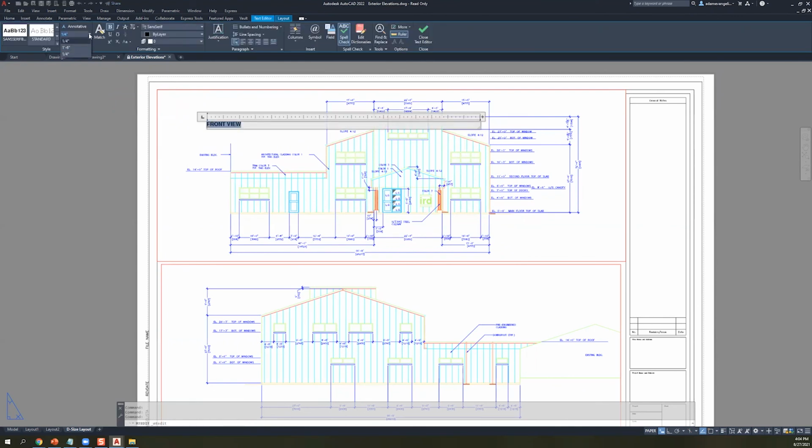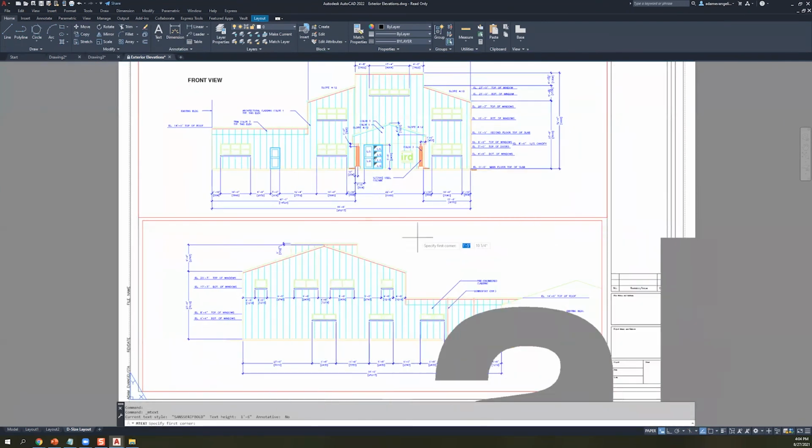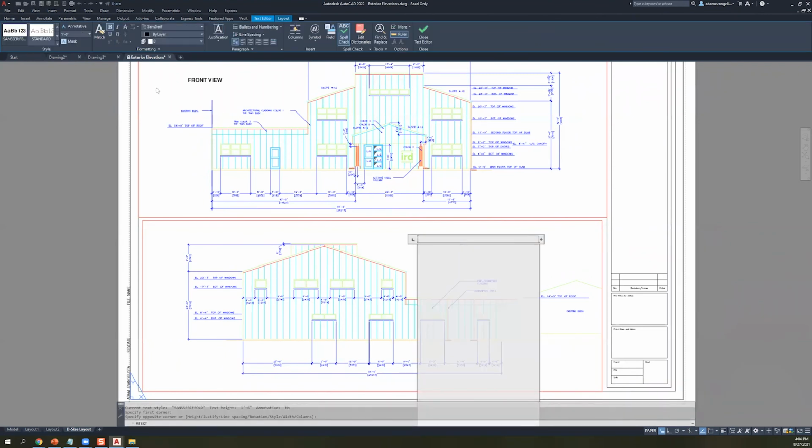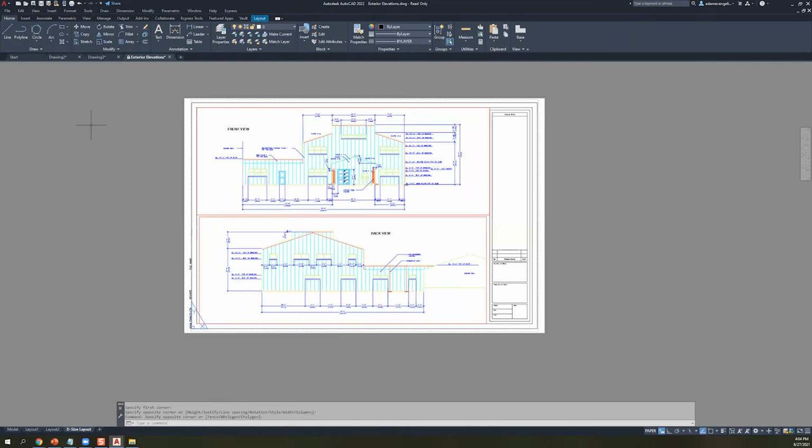And our font, instead of being like 1 foot tall, again, keeping in mind that our paper was only like 22 by 36 feet, it's pretty tall. So front view over here is now going to be 1/4. And that's what I'm talking about with the styles that you have to be aware of, right? And so you could keep using that annotation style if you wanted to, but just make sure it's scaled down so that it fits on the page that you need it to fit. There's some stuff you could do with annotative scaling and dynamic scaling and stuff like that, but that's probably another course, honestly, probably another conversation. So I won't get into it too much from here. Like that, right? And that looks about right. So just keep that in mind where and when you do those annotations, okay?